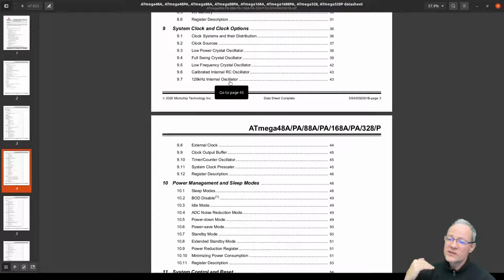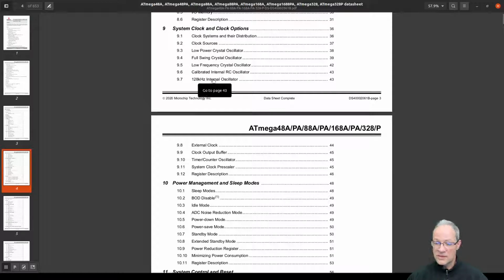But if you're doing a serial communication, then it's very important to have a very stable and very precise clock on both ends of the communication, of course, right? So for that, you sometimes have to do the calibration of the hardware in software, right? And that you can use with what's called the external oscillator or external crystal. So if you're doing something like that for an operating system, for example, then you would have to read through this section and see how these things work.